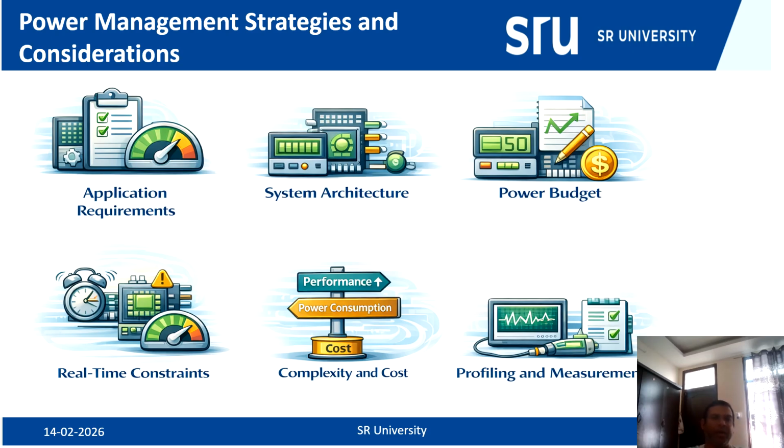Finally, profiling and measurement are essential for effective power management. Accurate power profiling helps to identify the power hotspots and validate the design assumptions. Tools such as power analyzers, simulators, and emulators enable designers to measure the real world power consumption and assess the effectiveness of implemented techniques.